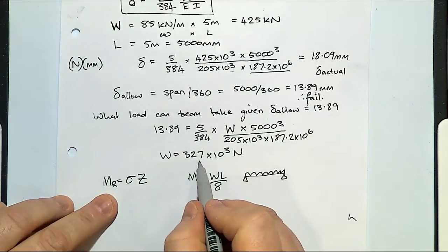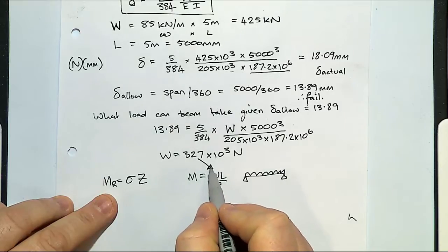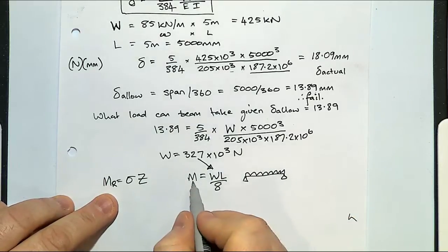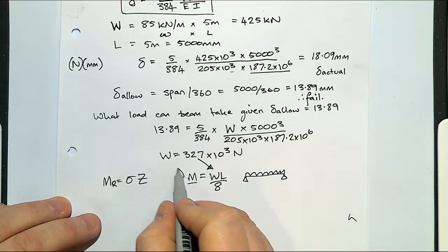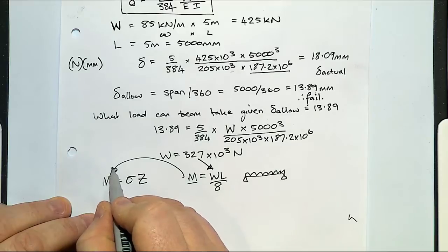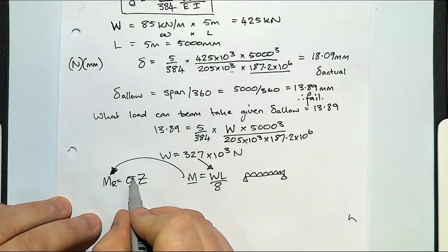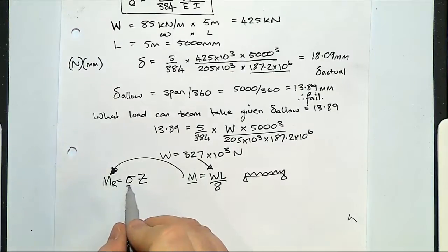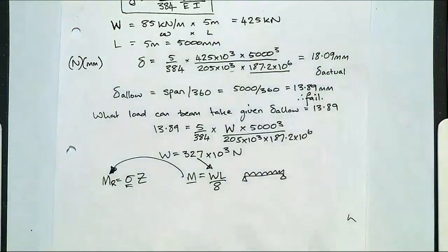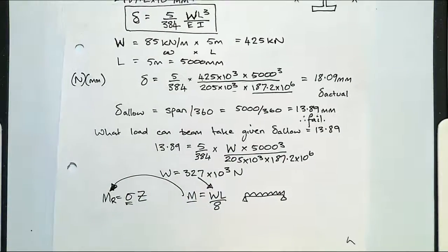So you can put your W into there, then that will give you the moment that the beam can take. You can put that M into there, and you can work out what the stress in the material is. You can get your elastic modulus from the table. So these are different ways of playing around with the formula to try and decide either what beam do I need or what deflection am I allowed. And so that's a bit of a reminder of what we did last week.